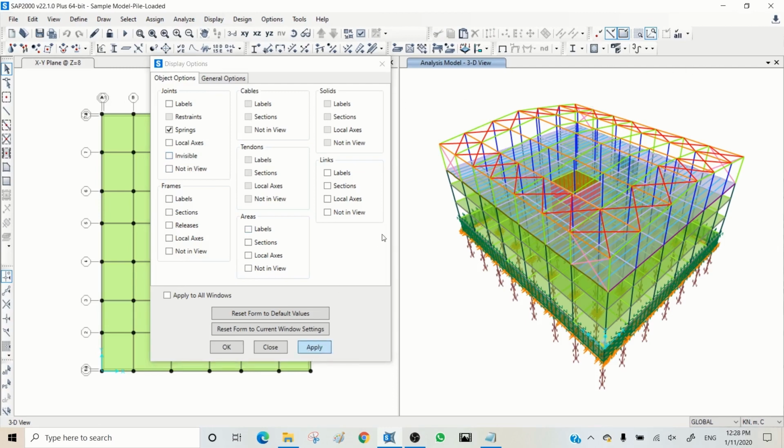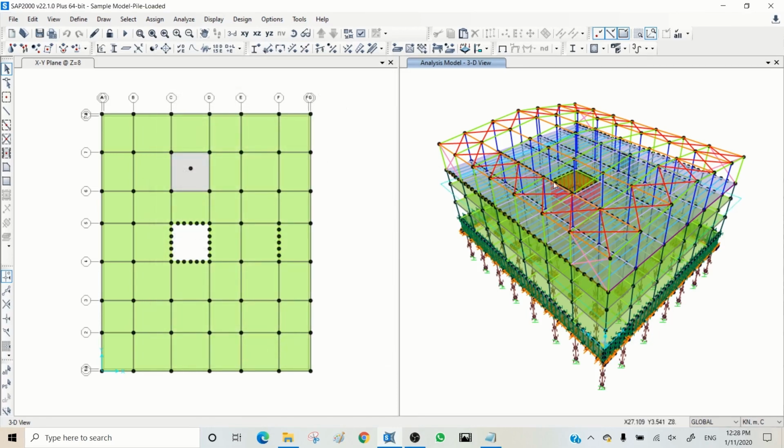Let's move on. So we removed our extra joints. Now what we need to do for the rest of the elements. Let's start from the lower level. So this is Z0. Here I have a wall and I have a column here. For auto meshing, generally I prefer not to have just 2 endpoints for a wall. It's better to subdivide your wall into more elements.